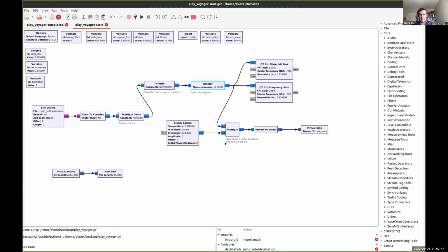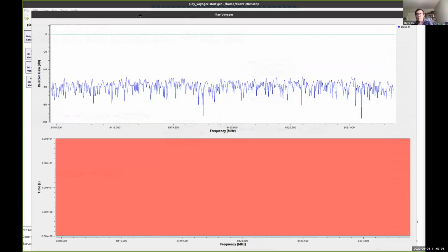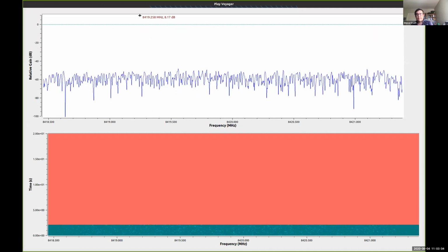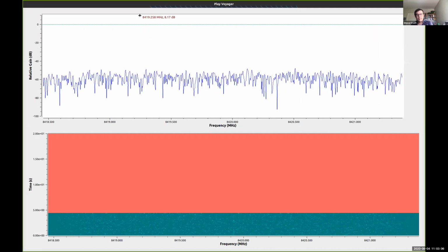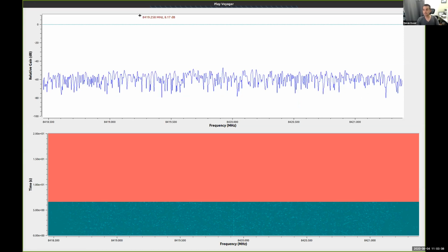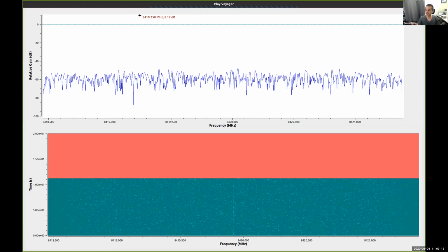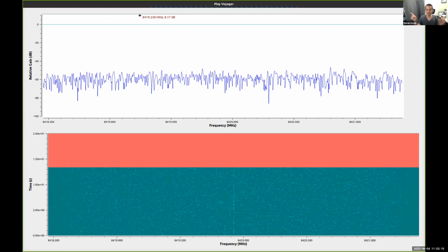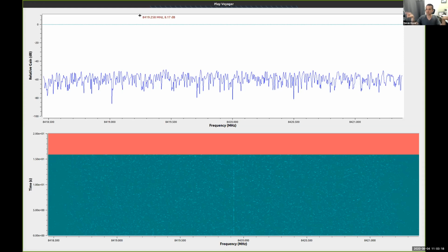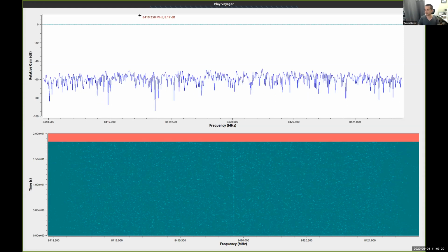It's also possible, Derek, that's the edge of one of the coarse channels. So there's this 3 megahertz scalloping in the Green Bank data that corresponds to the coarse channel width, and that drop in sensitivity there, I would guess, is the boundary between one coarse channel and the other. That may well be the answer, and we may only have one channel. And in that case, it probably still would be the band edges. It would just be from a different cause. It wouldn't be the radio, it would be the processing.